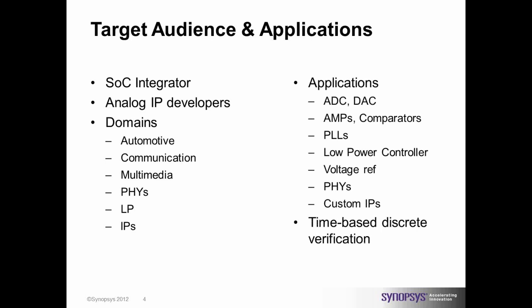And what kind of applications do we target by such a methodology? It's mostly about verifying components like ADCs, DACs, amplifiers, comparators, PLLs, low power controllers, voltage references, PHYs, and again any custom IP. Basically the idea is any time-based discrete verification component. So any component which works on time-based discrete sampling can be verified by using this kind of a test bench methodology.